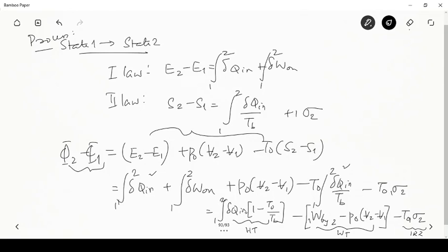So the heat actually seems to run a Carnot engine between the boundary temperature and the surrounding temperature and takes the efficiency there, and that efficiency is multiplied by dQ in. So the energy that comes in from the surroundings to the object, a fraction of it is converted into work and added to the object. So that is the change that happens here. This change is a positive quantity when this is positive, that is when Tb is greater than T naught. Okay.